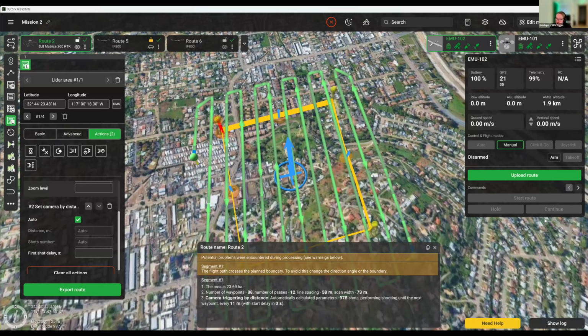You might also want to try, in your case with the Astro, doing the U-shape calibration. From what I've spoken about with some IMU manufacturers, there isn't really as big a difference as some of those who sell the LiDARs say regarding which pattern to do. As long as the IMU is woken up, as long as it's shaken up, so to say, then it should be good.